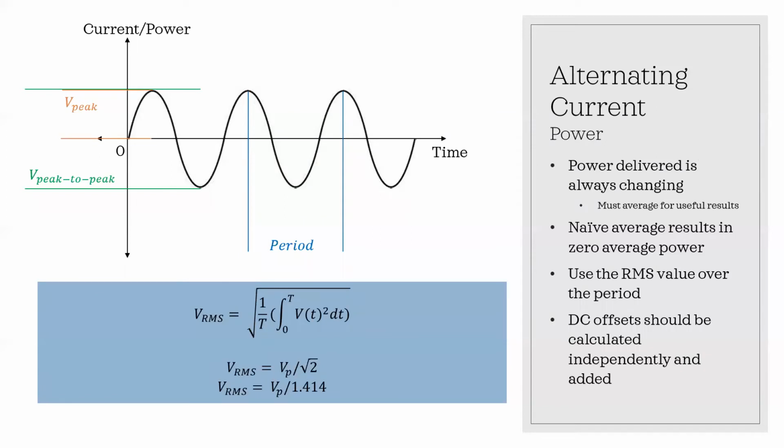Anyway, back to VRMS. It's where we take the root mean square of our time integral of the sine wave we're doing, shown in the blue box. So because it's a sine wave, it turns out that the time average is just 1 over the square root of 2. And now we can use this for any form of our wave, not just sine waves or cosine waves. And we can do this because of superposition and linearity of waves. And also, it's been proven, and we're going to go over this ourselves in the Fourier transform.